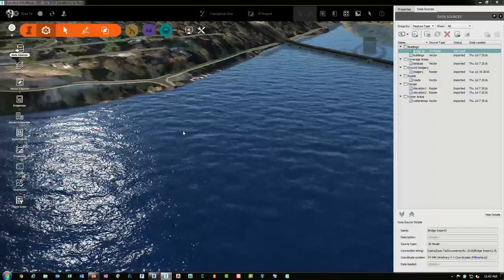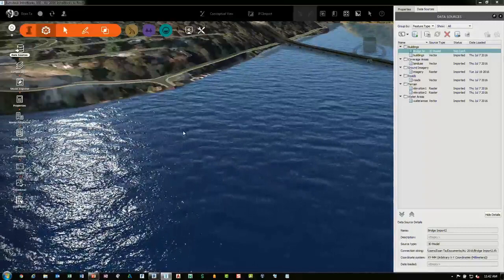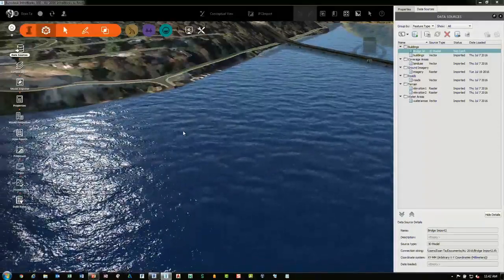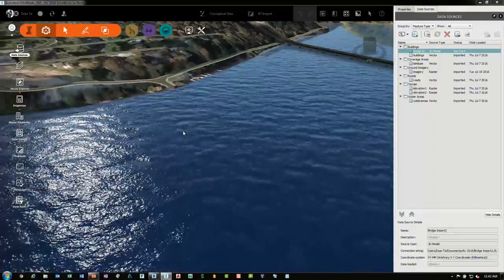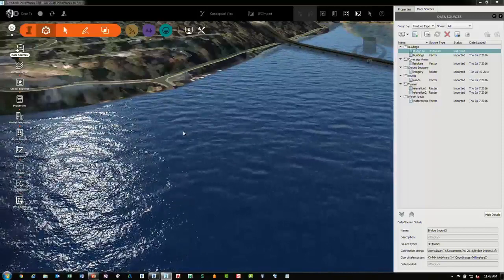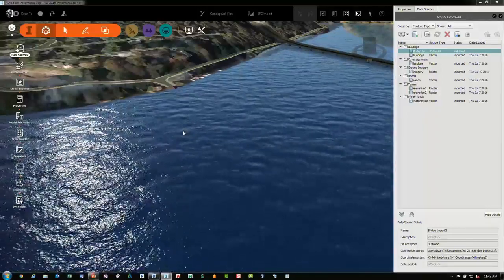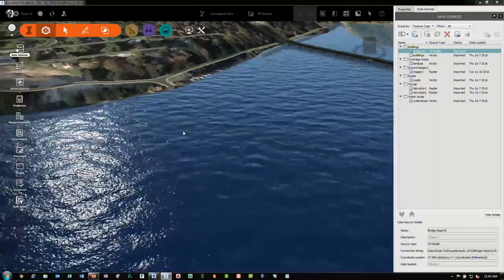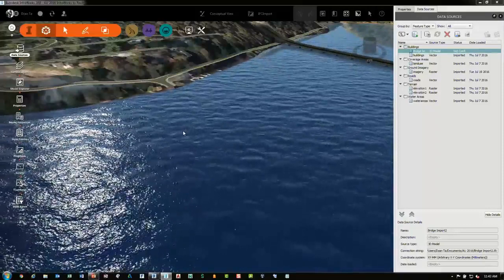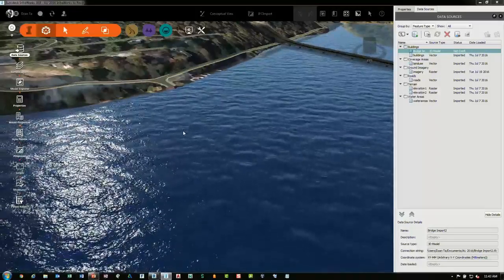And depending on the software that you're working with, some software accepts IFC files much better. For example, Navisworks accepts IFC files very well. Revit, taking an IFC file and bringing it into Revit is a 50-50 shot. Okay? And it's just very, very strange with the IFC file format. And so for InfraWorks, trying to take a Revit bridge and export it out as IFC and bring it into InfraWorks, I haven't been able to make it work.